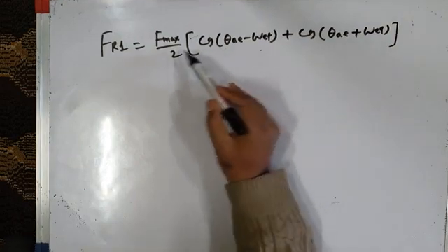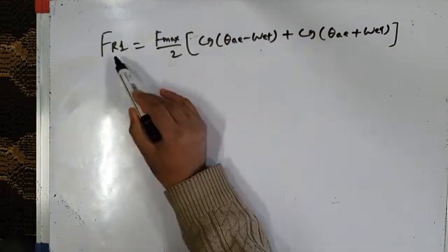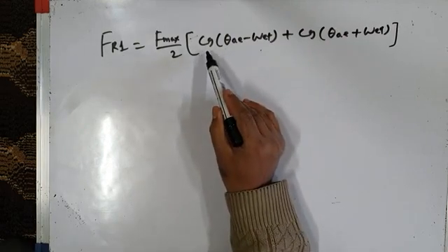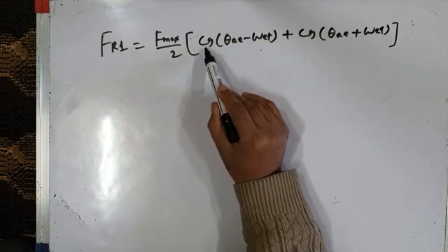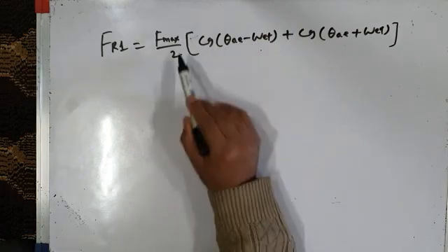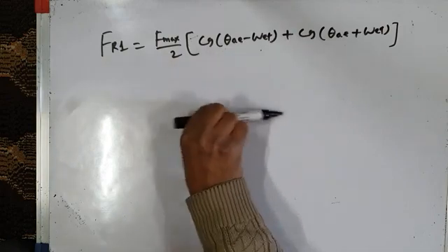Now here, this means the magnetic field or MMF produced by current flowing in the single phase winding of a single phase induction motor causes the MMF to rotate, say, in clockwise direction. Because what is theta AE? It's the air gap angle, and this theta AE is changing.